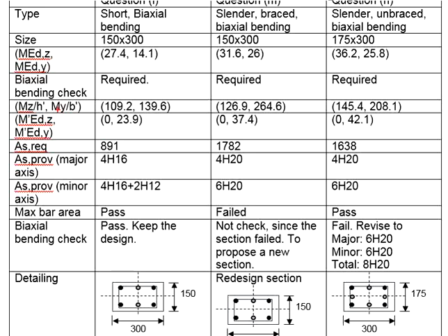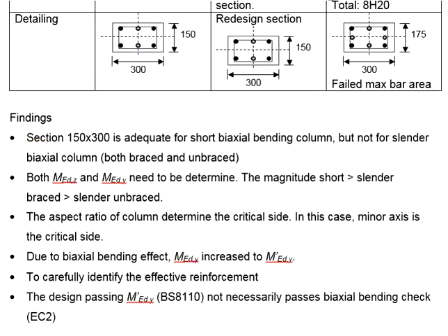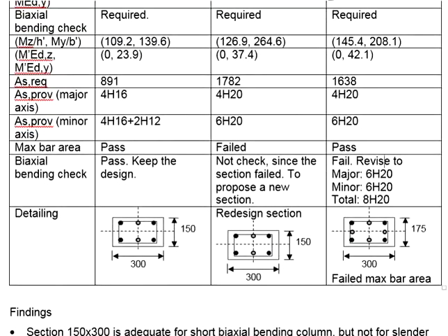In the case that the minor axis has a significantly larger moment relative to the major axis, this may also lead to the minor axis being more critical. We might not be able to immediately identify which side is more critical at first glance, but we have a proper calculation step for us to confirm which side it would be.